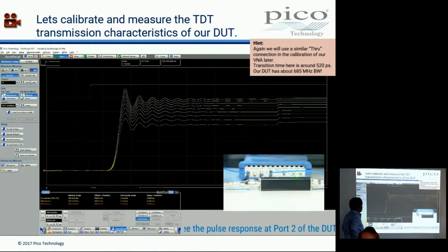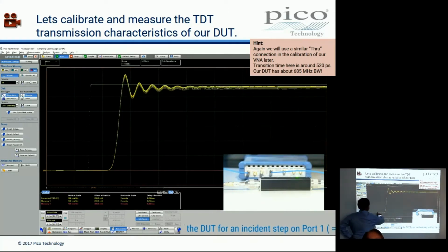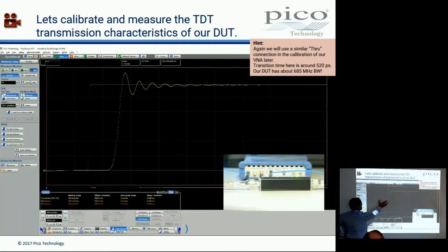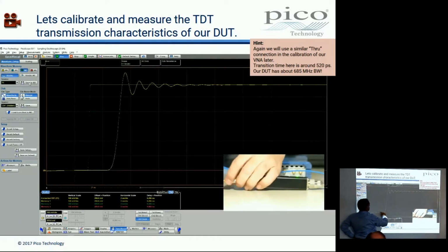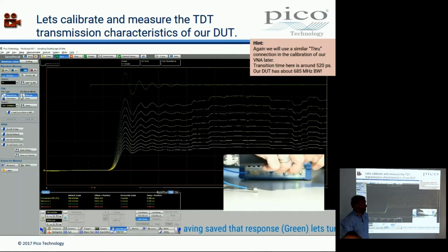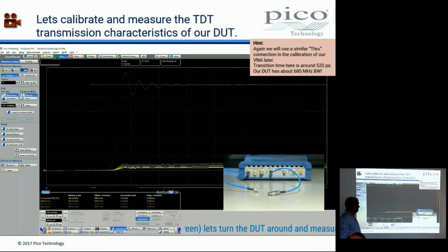Now, interesting. So this is the response to a step. Here is our 2 nanoseconds. We saw it, didn't we, on the scope? Well, we can now see it here. It's the same 2 nanoseconds delay, but on this high bandwidth system with a high bandwidth stimulus, we can see the pulse response of this thing. If you put an ideal pulse into it and look at it on an oscilloscope, that's what you'd see as the pulse response of this network.